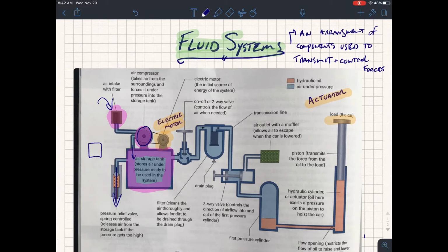The word valve is really important for you to know, and you will be responsible for being able to understand different types of valves. The first valve that we'll take a look at is this one right here. You twist this, the plunger moves down, and you can see that as it sits in here, it can block off air from entering the rest of the system. This is going to be closed when we want to pressurize the tank, and when we want to move that pressurized air out, we're going to open it.